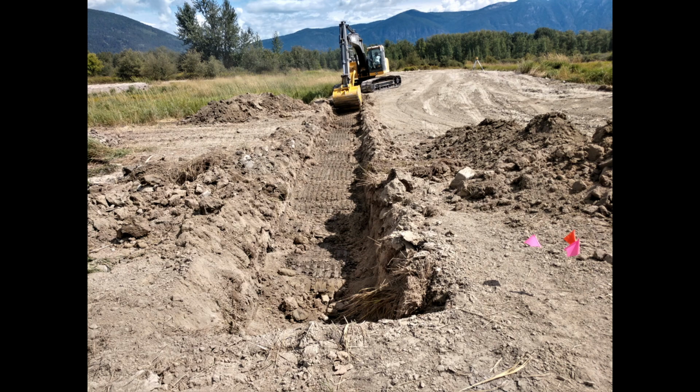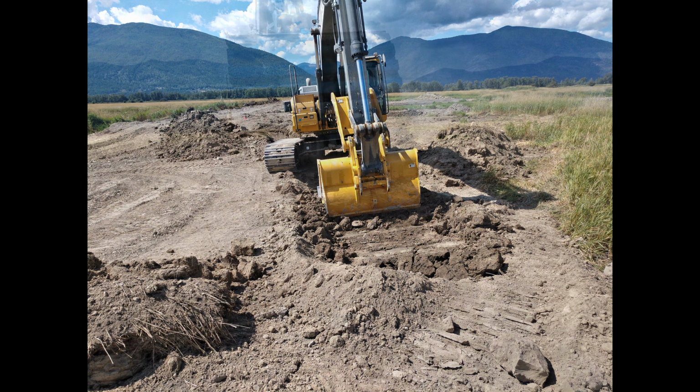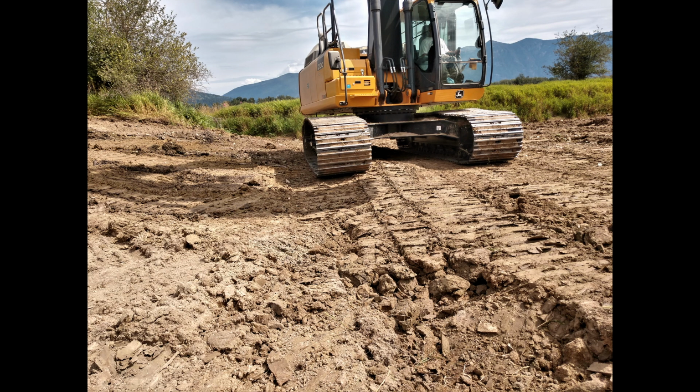The excavator digs the trench across the width of the ditch and keys it into higher ground on either side of the ditch. Soil that is high in clay is placed in the core trench in 6-inch thick layers, with each layer being compacted using the bucket on the excavator. It takes time to fill the trench with clay and to compact each layer of clay. Most of the clay needed to fill the ditch is obtained by digging a borrow pit on higher ground near the wetland we're building. The excavator operator uses the weight of the machine to compact the layers of clay placed in the trench to form the groundwater dam.